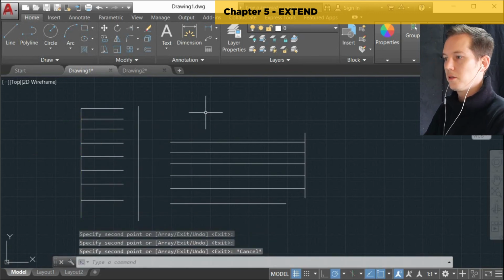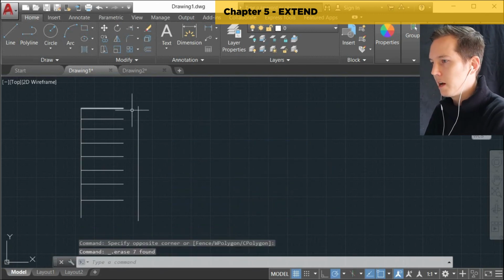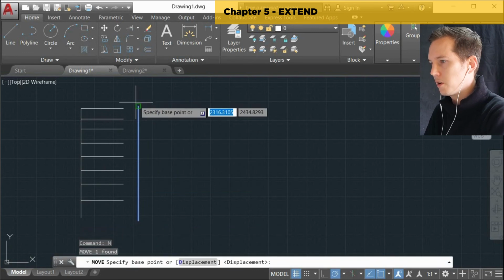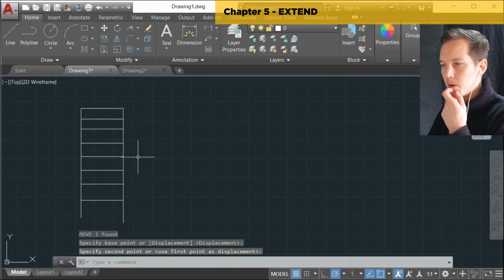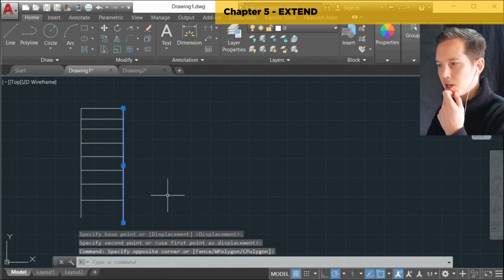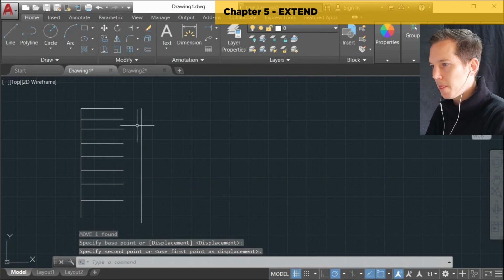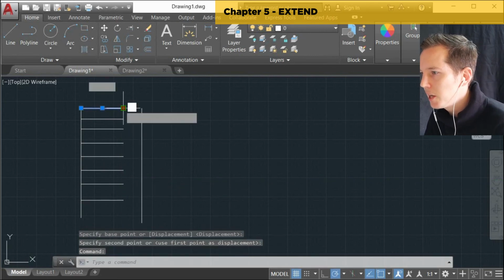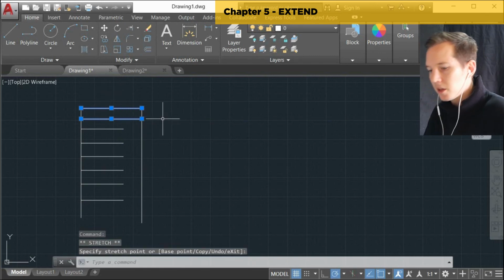Okay, don't draw steps as badly as that. It takes some more time to do it. And then let's say you had it over here, and then you decide, oh, it's a bit narrow. I've got to get 2 people up this flight of stairs. Maybe I should make it a little bit wider. So I'm going to move this over, and then I could click on these lines individually and grab the grip and then drag it out like that. That's a little bit tedious.